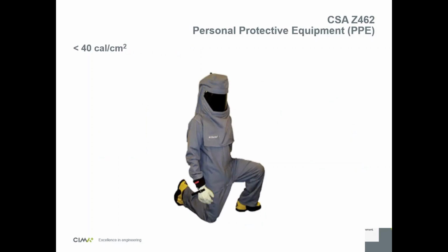Then this is a kit that's designed for use between 12 and 40 cals. As you can see, the suit is pretty large and encumbering. With the large hood, it can be hard to see, and it can be hard to do precise maneuvers in the switchgears.